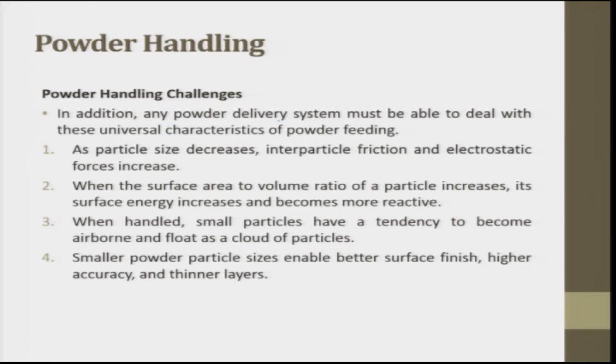In addition, any powder delivery system must be able to deal with these universal characteristics of powder feeding. As particle size decreases, interparticle friction and electrostatic forces increase. So that is why you have agglomeration. When the surface area to volume ratio of the particle increases, when surface area increases, at nano size, its surface energy increases and becomes more reactive. If the surface area increases, the surface energy increases.